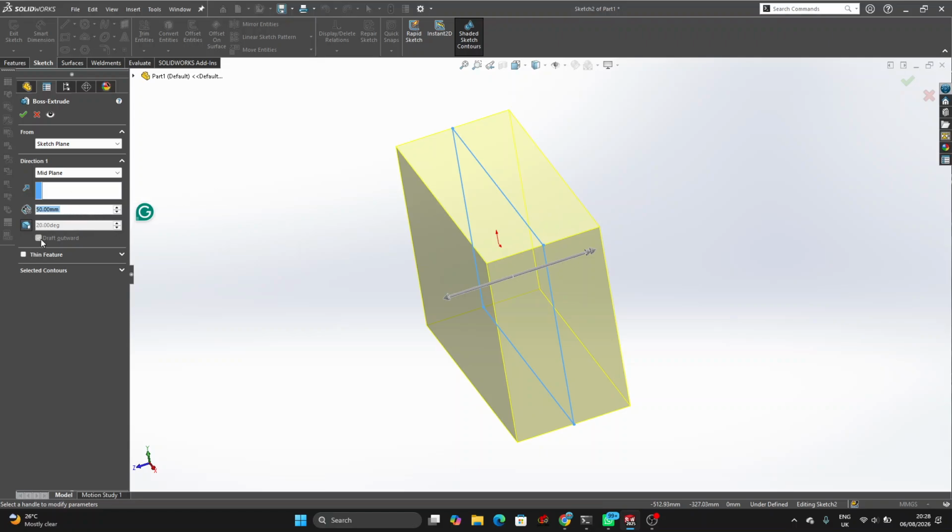into two. It started from the sketch plane and it is going 25 in both ways. It is going 25 in the first way, 25 in the second one. That is for the midplane option. So you can edit it, increase it to 60, however you want. So I wanted to use that to explain the mid-plane option. So I've explained the mid-plane option.